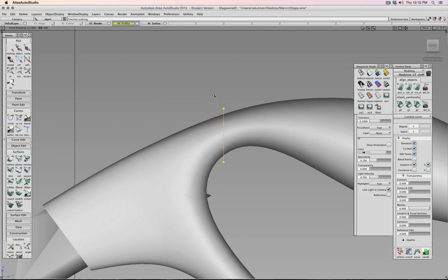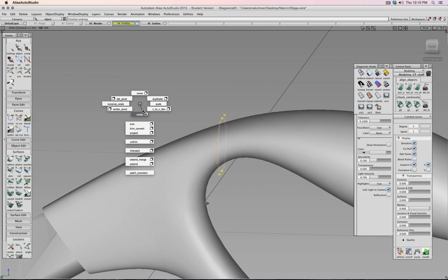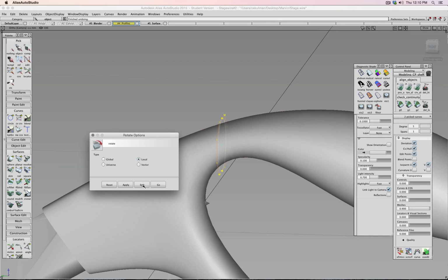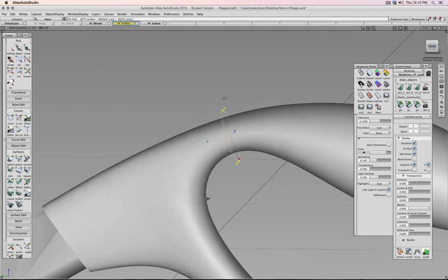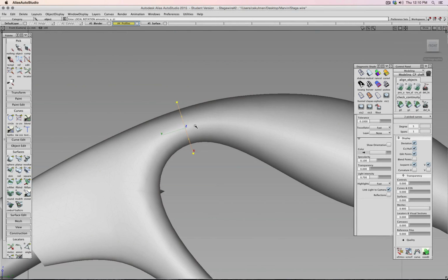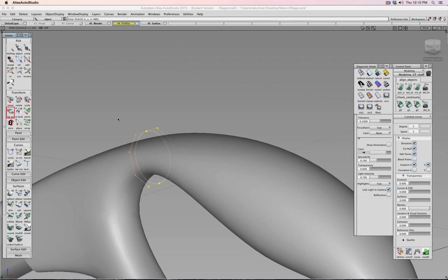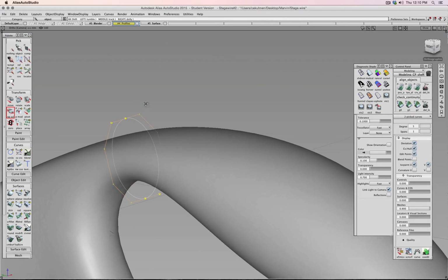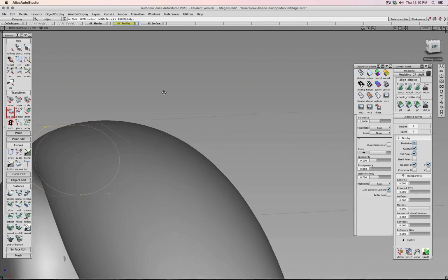rotate it, whoops, wrong direction. Yeah, let's go to rotate, select the menu, local, because then it's Z. Okay, so I'm going to try for the moment to see if I have to position this curve here. And I can already see it's a little bit too big, so I'm going to scale this one a little bit. Maybe use the non-proportional scale, and I think left mouse button is along the X axis. Oh, that's a little bit jumpy.